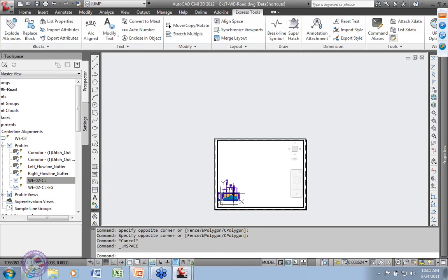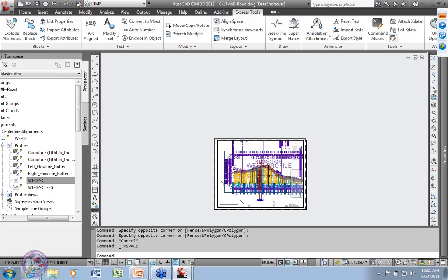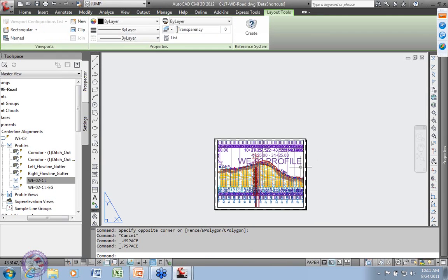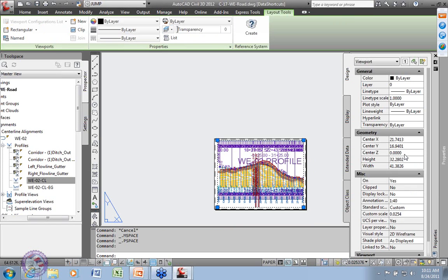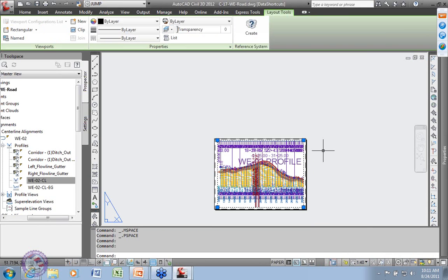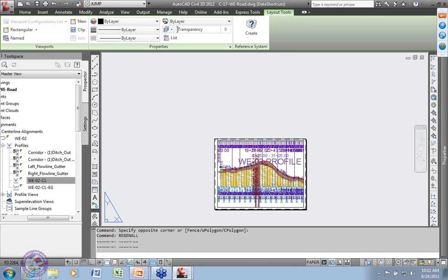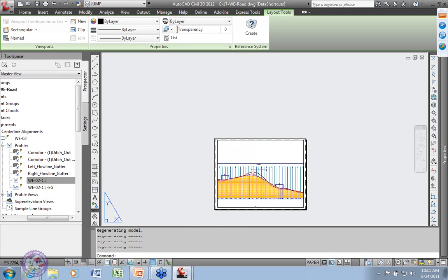and zoom. Yeah, that should work about right. Hop back out, grab this. Okay, and we've all done this a million times, and this is a viewport. It's got properties. It's got a scale. Hey, 40 scale will be good, right? Okay, so I set my scale, do a regen all, and hey, everything turns out better.